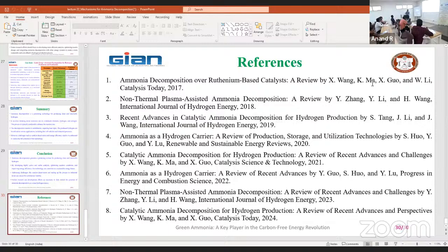Maybe the same thing can be done for our high temperature corrosion here. The Bombay bridge involves low temperature corrosion, and here you need to do some kind of study for high temperature corrosion. We have a corrosion center at our NADC. We are able to do both low temperature and high temperature, because from the fuel tank to the pump is low temperature. When fuel is injected into the fuel injector, then the piston rings, piston, cylinder liner, crankshaft, camshaft, even the valves are exposed to high temperature. So we need to do the high temperature corrosion study also, to see how ammonia behaves at high temperature.